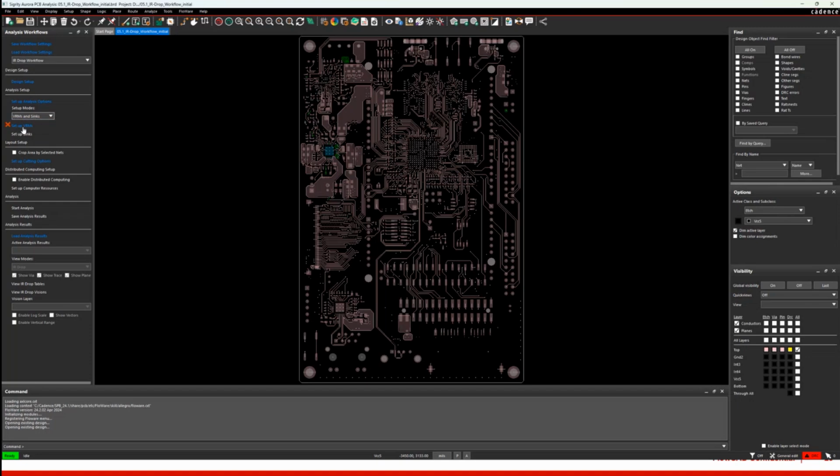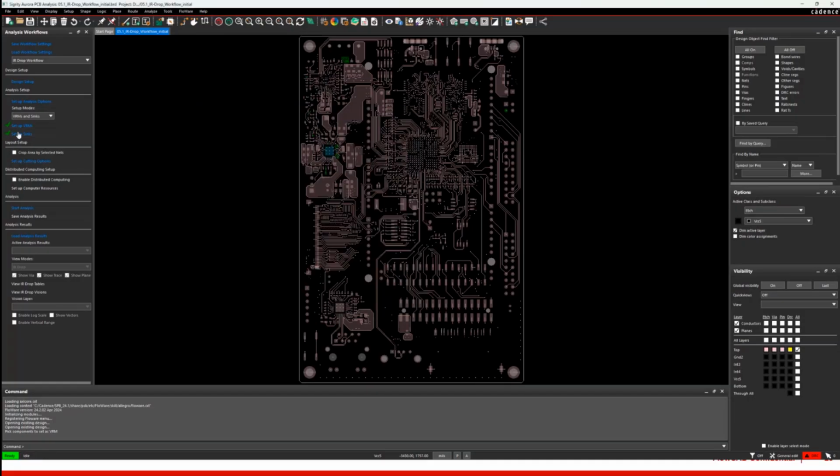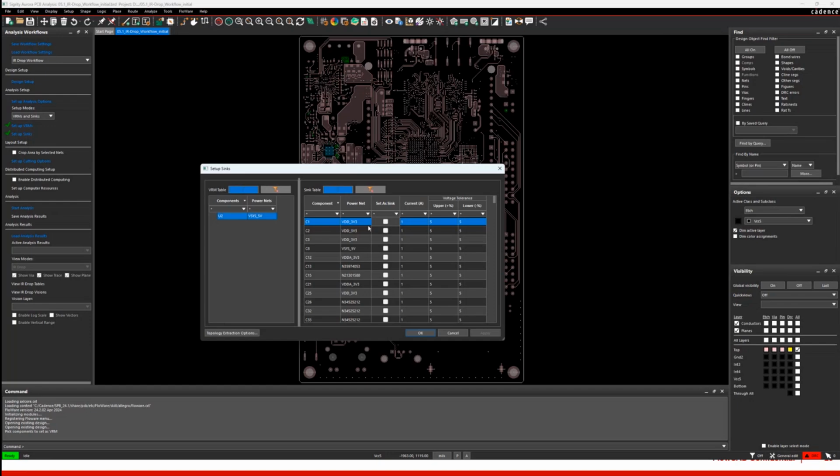At first, I want to show you once a simple way where we only have the voltage regulator. For example, in this case, I can sort the voltages here, and this one I want to use, the VSys 5 volt, and that directly shows me all available components that are attached to this power rail. And here we have our U2 as our voltage regulator, and say okay. The thing is quite simple. You can also select all that are available here.